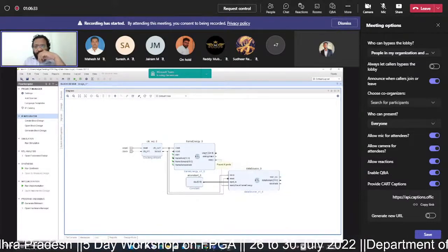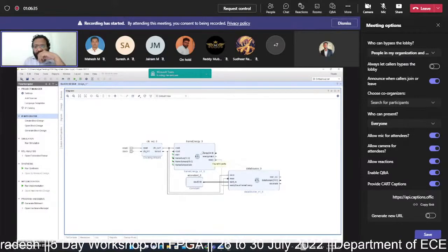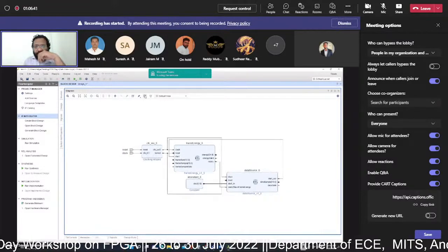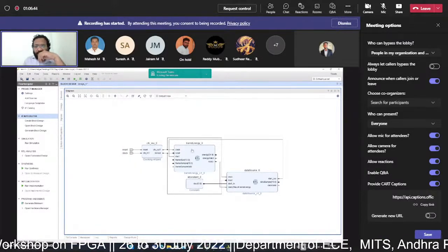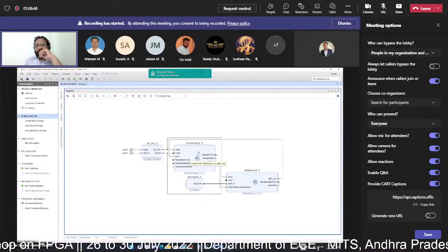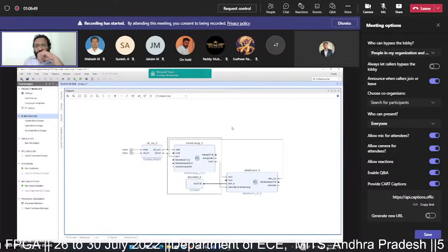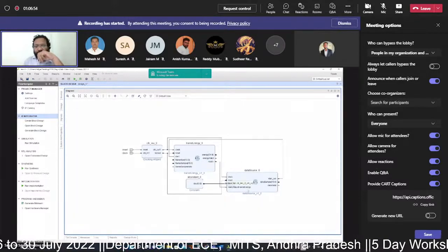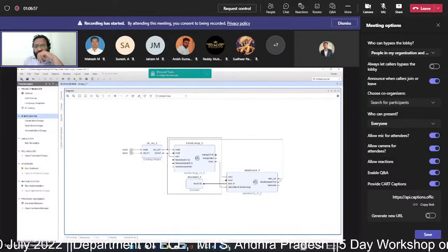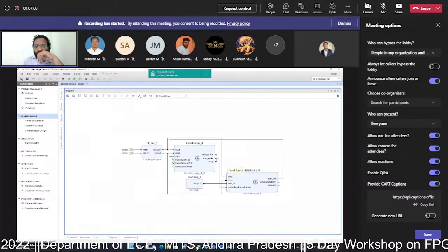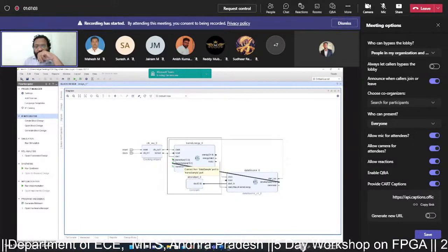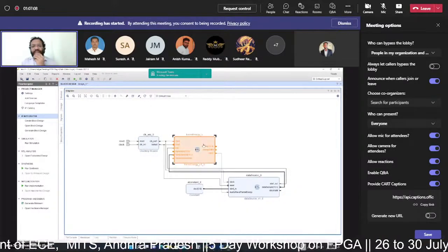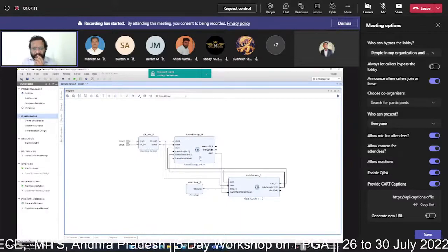So the triggering will happen from the output of start_out of the data source that is connected to the start input of the frame energy module. After the frame energy module is triggered, it will switch from idle mode to the computation mode. In the computation mode, the frame energy module will wait for the data samples to arrive from the data source. So now connect the data sample output of the data source to the frame sample input of the frame energy module. And how will our frame energy module know whether a valid sample has arrived or not?